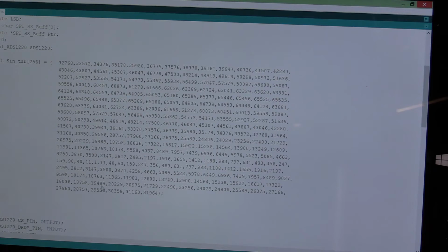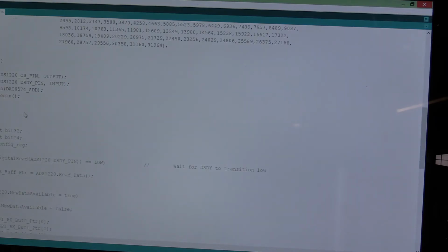Anyway, what I've done is I've included the wire interface, of course, for the I2C. So in the code, we saw that this was using address 98. Control code is set to 34, which was used in the example, and as we've already looked at going through that code and also the datasheet, we're going to probably change this because this is doing a broadcast. This is the sine table, so that's what we'll look at in a moment. In the setup, we've added the wire begin with the DAC address in it so that it sets up the initial address. That's the only thing we've added in there that's new.